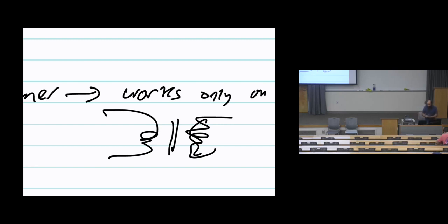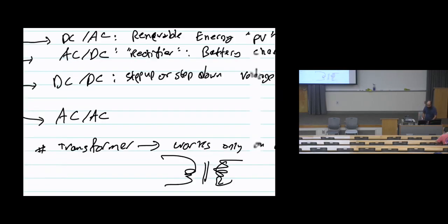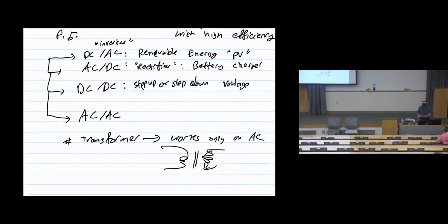Okay. Since the equivalent circuit of the transformer involves inductors, and inductors in DC are a short circuit, this makes the transformer unsuitable for stepping up or stepping down DC. It can only work with AC. So the best way to step up or step down is using a power electronics device, the DC to DC converter. That's why I said that nowadays, with the invention of power electronics, we can no longer say that we cannot easily step up or step down DC voltage.